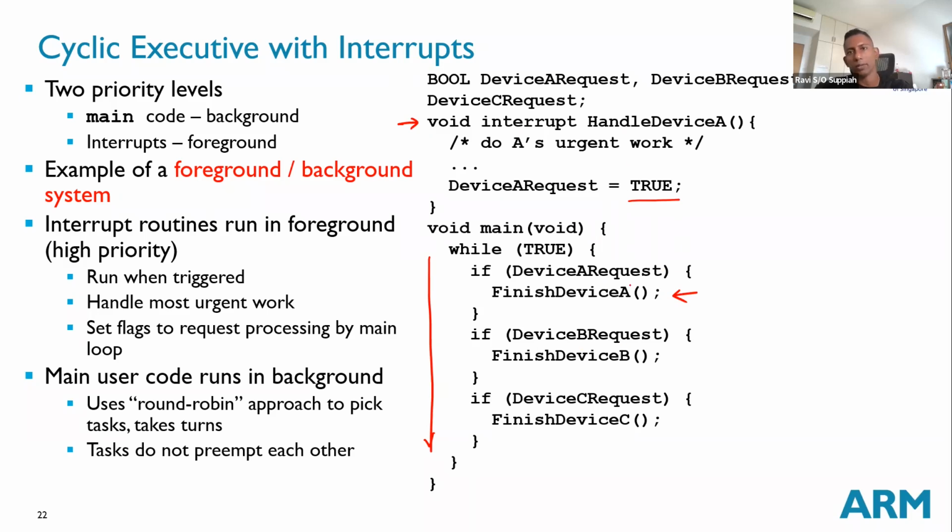Okay, so if you recall, one of the things we discussed in EPB2 is your interrupt handlers should always be as short and focused as possible. When we say short and focused, we basically mean that we want to know what is really urgent, what is really important in the interrupt. And that is usually capturing the new data and storing it somewhere.